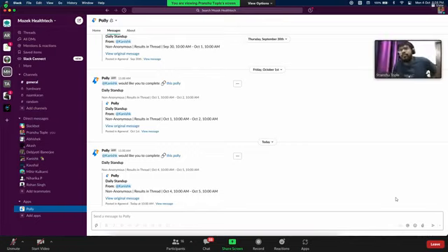If you tune AMCL once according to your robot and make it for a bigger environment, and it can localize itself in a bigger environment, then in all other smaller environments it will work perfectly. But if you tune it for a smaller environment and expect it to work on a bigger one, it won't work. So make a simulation environment which is huge and try to tune it there. Once it is tuned, it can work anywhere.